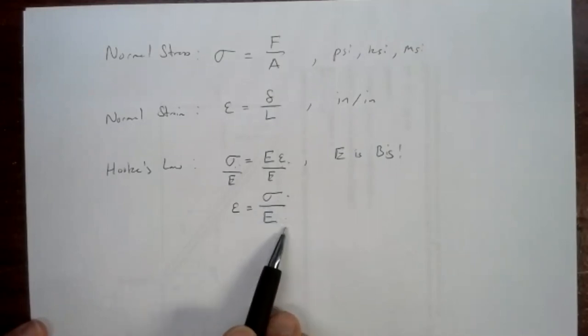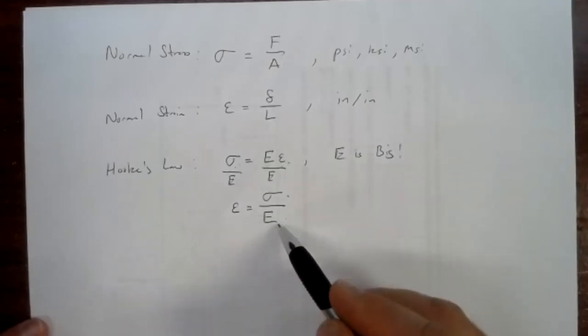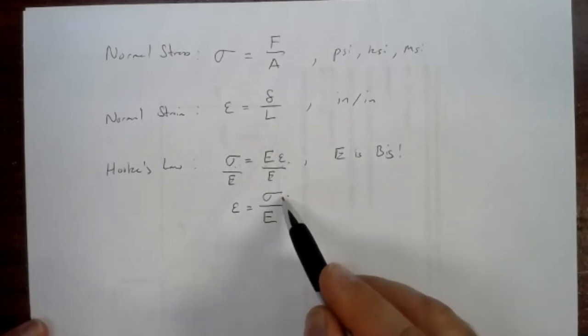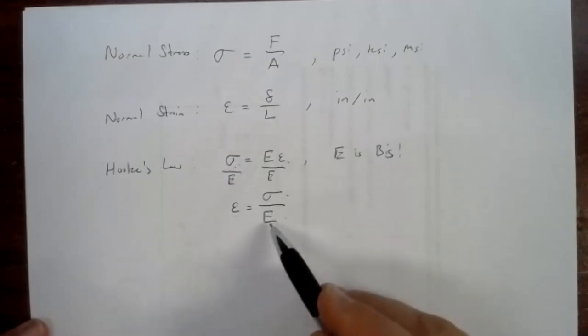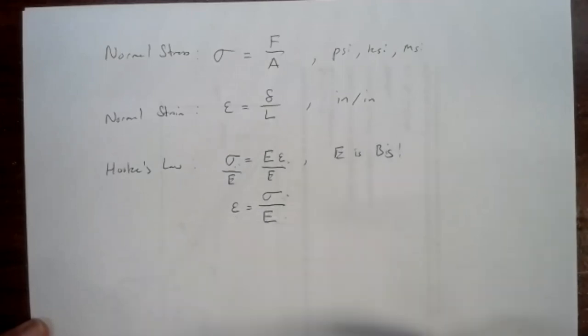On the other hand, if we have a very flexible material, a plastic material that can stretch very easily, that changes its shape very easily, the modulus is a lot lower, because it doesn't take as much stress to get a significant amount of strain. So the Young's modulus is a material property.